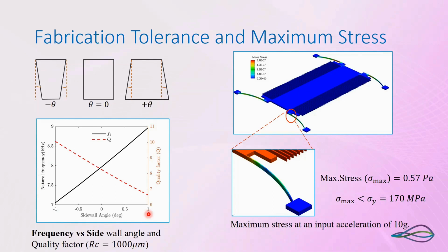and the corresponding frequency change, you can see around 12% that will come, and even the quality factor basically from the combs. If you just see, there are combs over here. One is a fixed comb, another one is free, and it moves this way. So these two combs will combine like this, and it will create a squeeze film damping kind of dissipation.